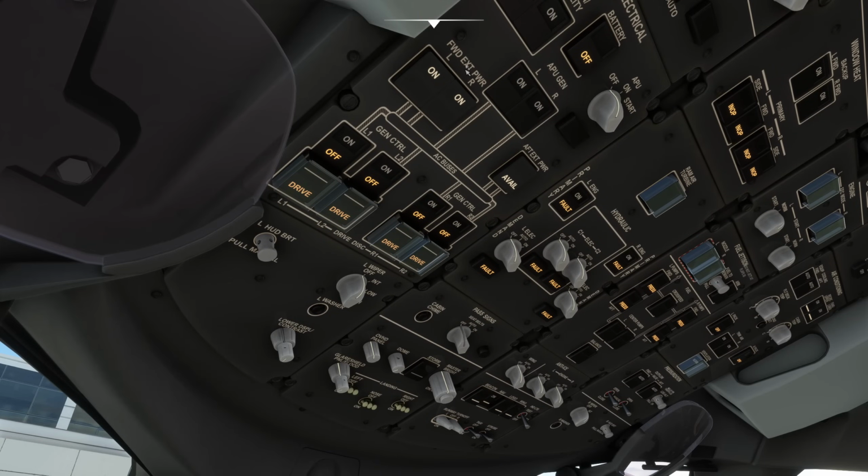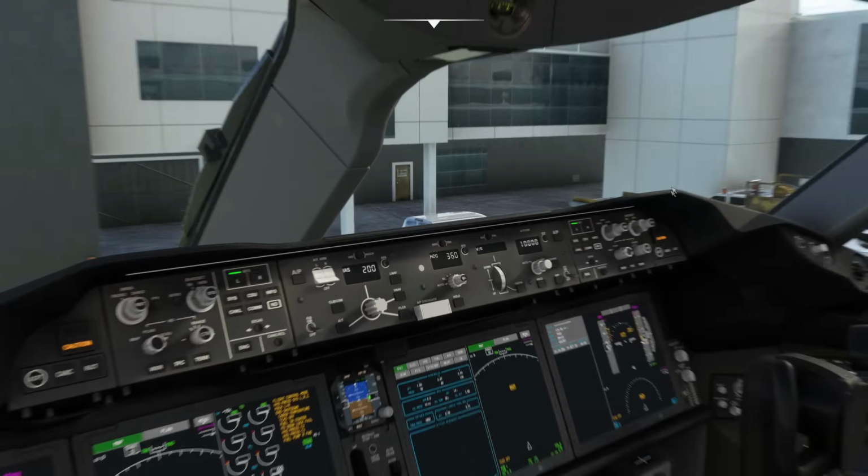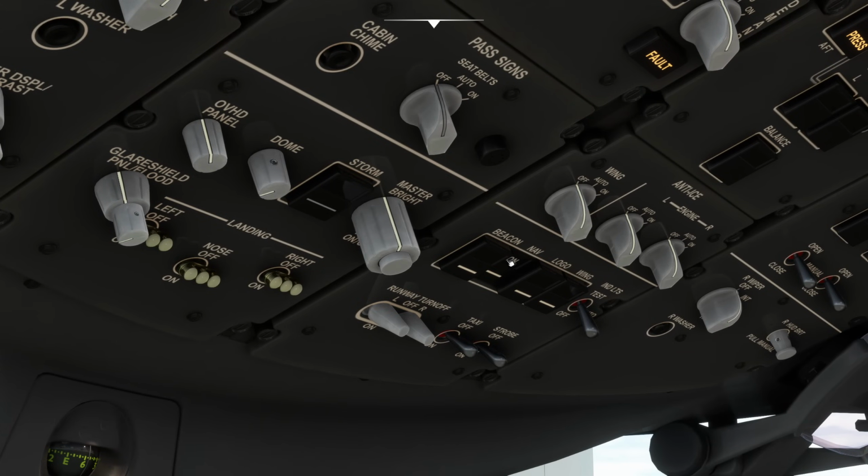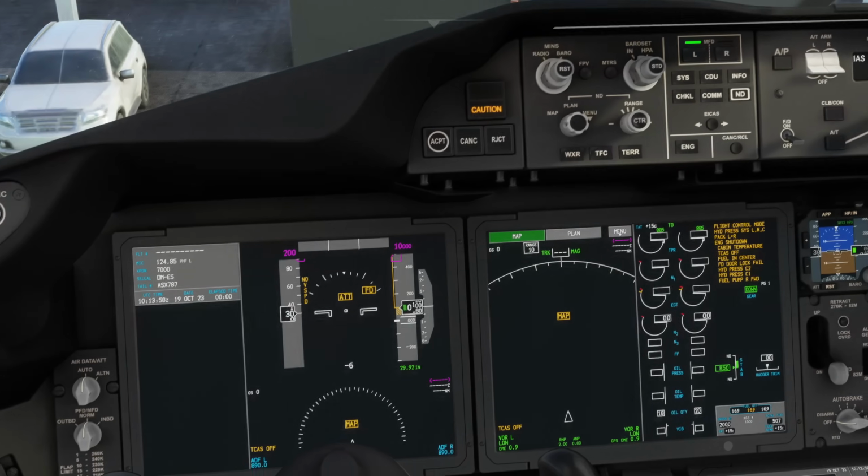This is part of the flow that you would do on the flight deck, but we'll talk about that in the next video. The reason I've done that is so that we have the nav lights on. So I've also turned those on over here, which enables us to check that we have the red, green and white tail light showing when we do the walk around. You don't actually need nav lights when you're flying around in daylight, but on a long-haul aircraft, it's quite common to fly the aircraft through the night. Even if you start in the day, you might fly through the night and then back out in the day on the other side. So yeah, it's something that you would want to check.